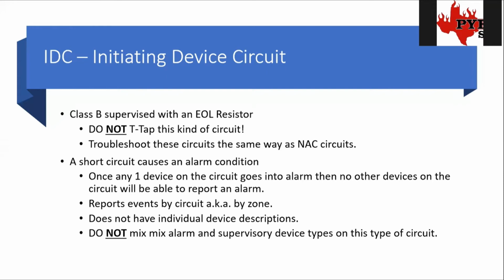So one area we still use them for conventional panels is apartment complexes where we're just doing some sprinkler supervision, and then we'll go around the apartment complex and just monitor all the different panels at each building. That's a very cost-effective way to get a system like that done that leaves each building standalone without having incredibly high prices. Also, kitchen hoods work this way. All the sprinkler devices work this way. And we monitor all those with monitor modules. Anything we do with a monitor module, that secondary side of the module, is one of these IDC circuits.